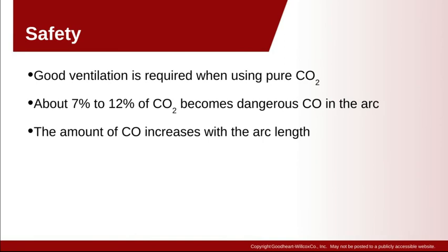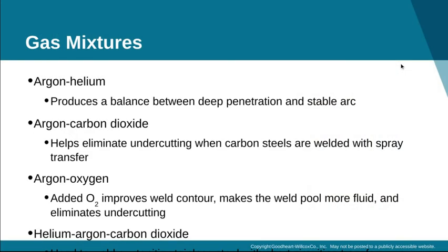Good ventilation is required when using pure CO2. About 7% to 12% of CO2 becomes dangerous CO in the arc. Carbon monoxide. The amount of carbon monoxide increases with the arc length. Again, I don't really think that'd be an issue unless you're welding over your head and it's falling on your face, or you're right next to your weld, breathing it in, which wouldn't happen.